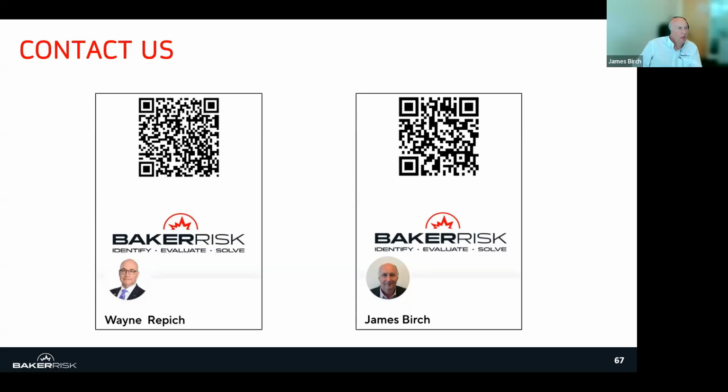There is no statutory or regulatory guidance that I'm aware of. I know certain operators within oil and gas have a requirement for, I think it's a minimum of 3 barriers to be present. And I think the policies tend to be only that at least 2 of them should be engineered protections. So in the example that I showed where we talked about only having 1 administrative barrier on one side and 1 administrative barrier on the other, that would not be considered acceptable.